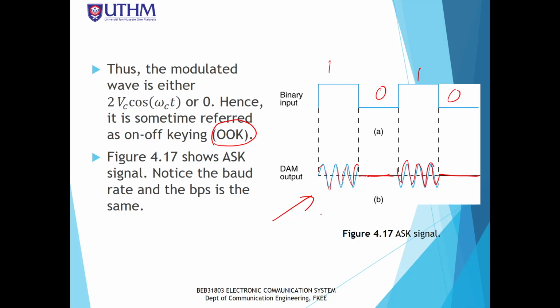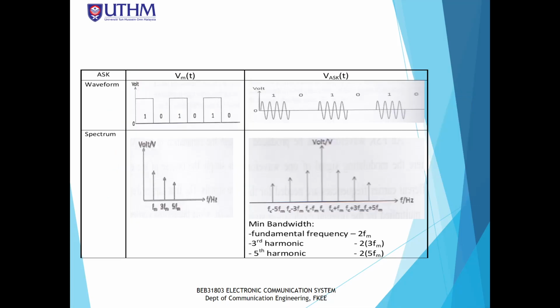It is also called OOK. You see that it looks like a switch turning on and off. So this is the pattern of ASK. Notice that for ASK, the baud rate and the bit rate are the same, because we are using PCM.